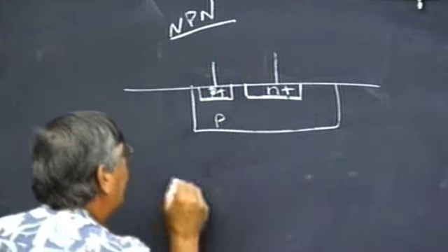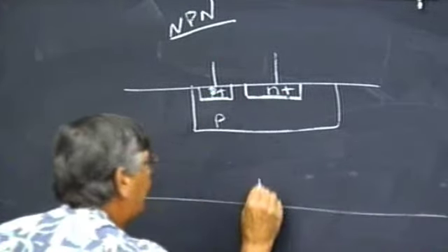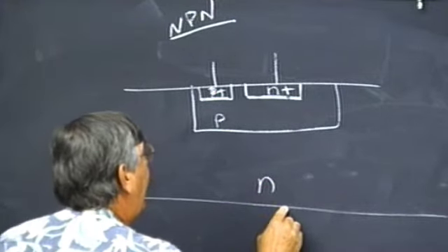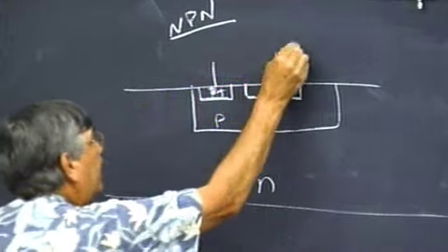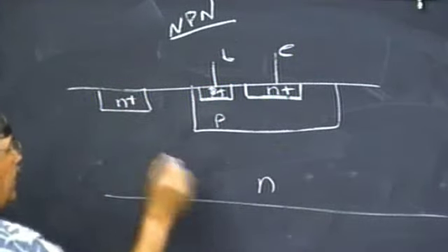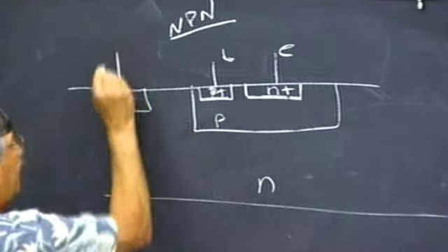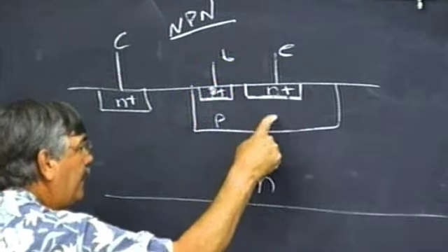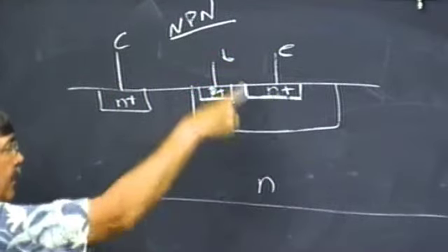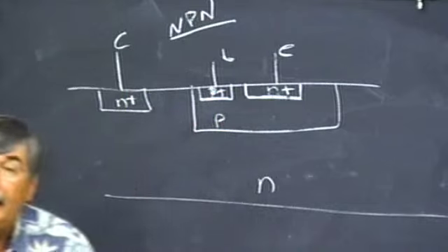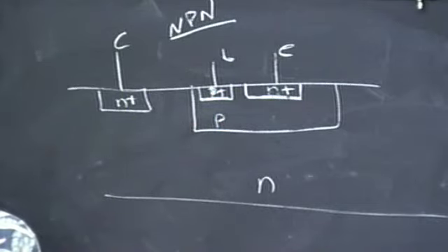All of that is typically then done somehow into a region which is lightly doped, which is the N-type collector. And so this will be emitter, base, and then we will need a heavily doped contact somewhere. All right, so this would be the simplest emitter base collector, vertical NPN, and then the currents would have to go sideways. So this is the simplest thing you could imagine. It already has problems, okay?